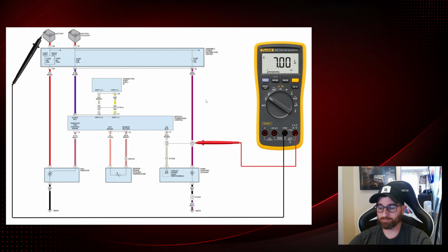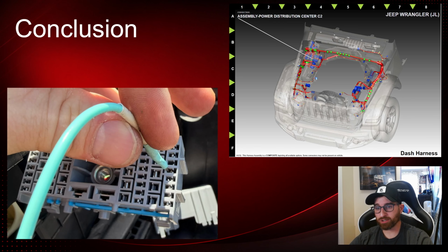I was able to test it. So this one pretty much was just a spread terminal. We fixed the terminal and everything was good after that one. But a little interesting case study, just showing you my thought process and workflow on diagnosing this one. Still very odd that this one had a spread terminal, but this is a good note. If anyone else runs into one of these codes or is dealing with a similar issue, definitely be a good note to check terminal tension throughout the entire circuit.